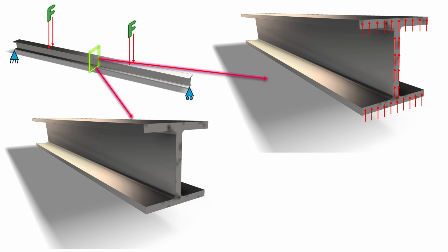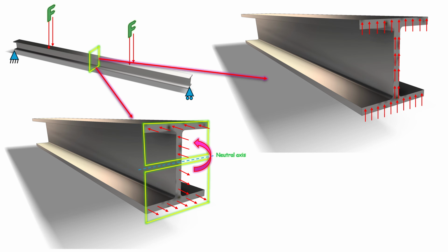If we consider the neutral axis located at the centroid of the cross-section, then applied forces result in the upper fibers of the beam going into compression, and the lower fibers going into tension. These internal forces are equal in magnitude and opposite in direction about the neutral axis. They do not create a net force, but together they produce a couple, which is known as the bending moment.